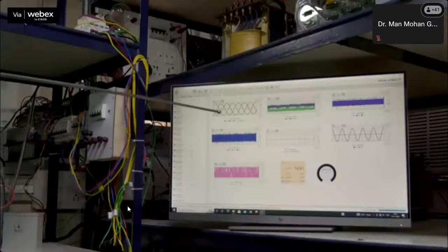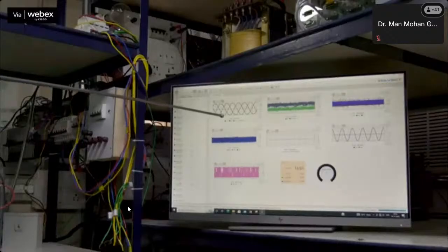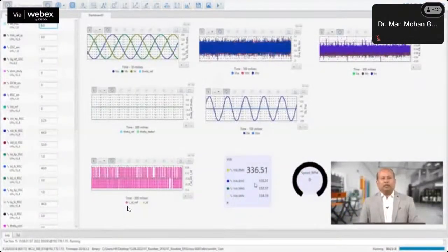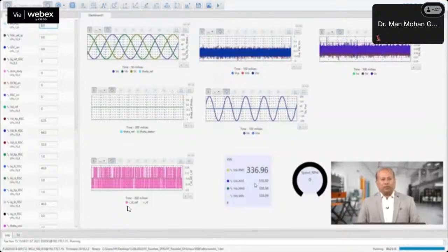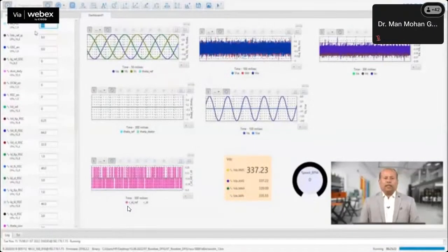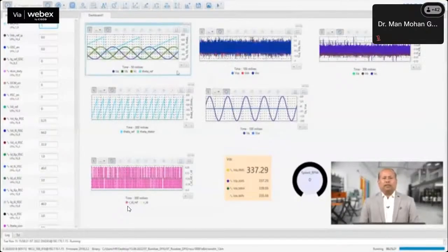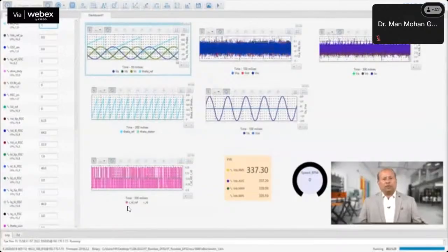The main and the rotor branch circuit breakers are switched on and the DC link is charged initially to 340 volts. Then we enable the phase locked loop and check the reference theta with the phase A voltage.